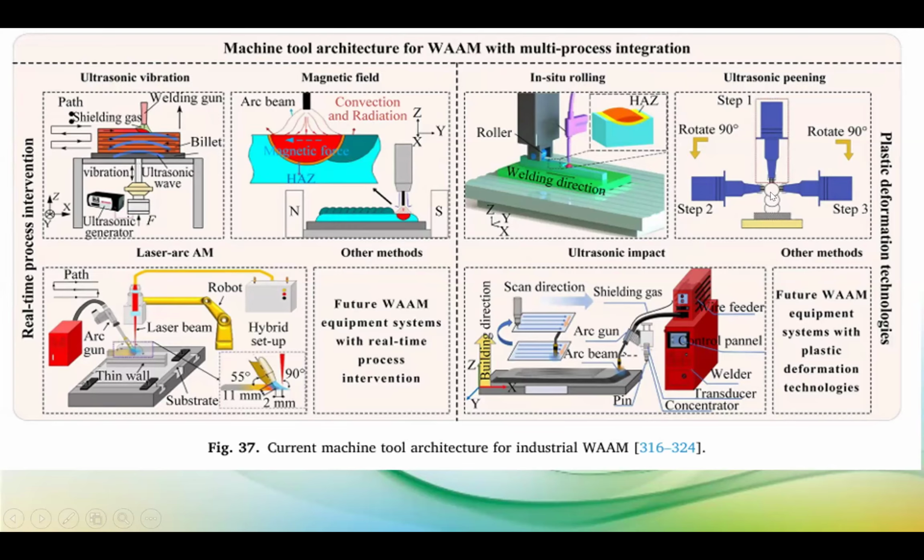The welding torch has some limitations. The arc width is a limitation. Normally, we cannot control the width of the arc easily. Our control of the arc is not easy in the case of a thick welding torch. Here, that limitation can be adjusted by utilizing an additional laser beam along with the welding arc. That is one advancement in WAM.